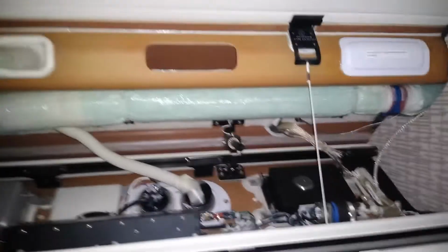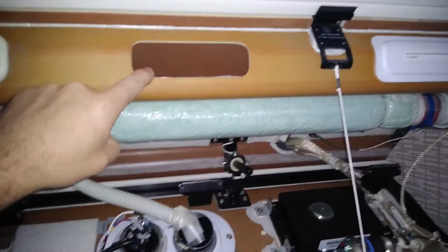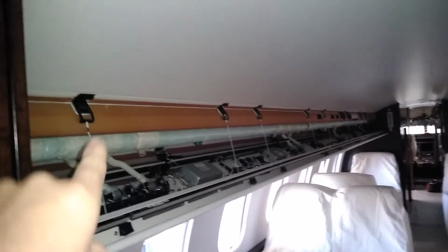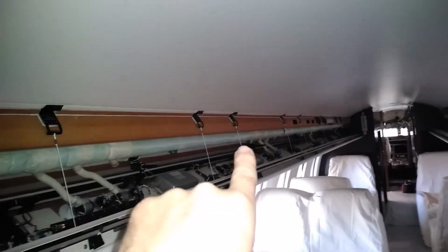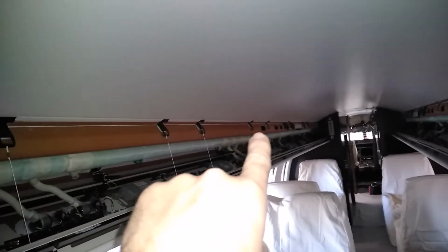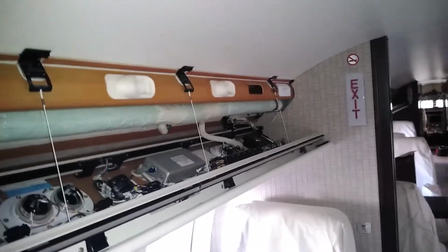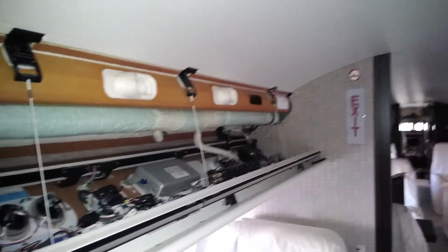Now the return air that gets recirculated gets sucked out of the cabin through here. This is the return air duct. That duct runs the length of the cabin. That green one is your Gasper air. You can see the individual taps going to individual Gaspers. This one up here, that is the return air duct. That is where the air from the cabin gets recirculated, and it goes through ducts down under the floor and ducted to the back of the plane to the mixed manifold to be filtered and recirculated into the cabin again.